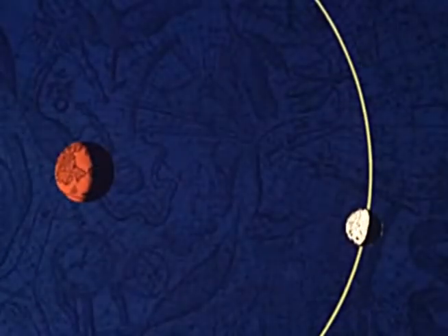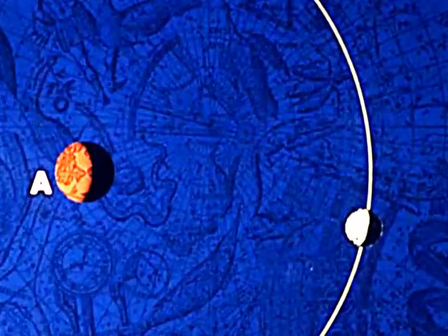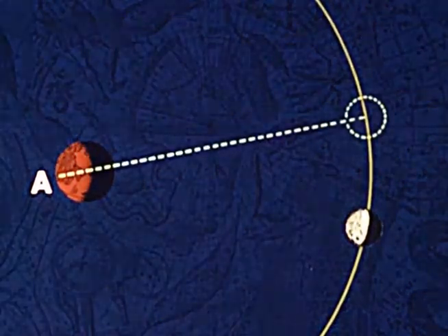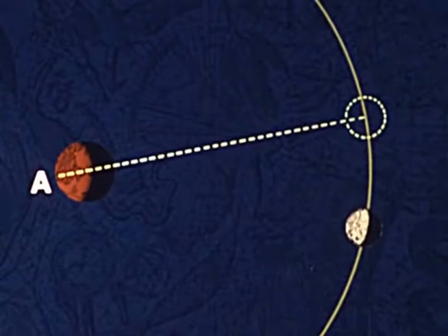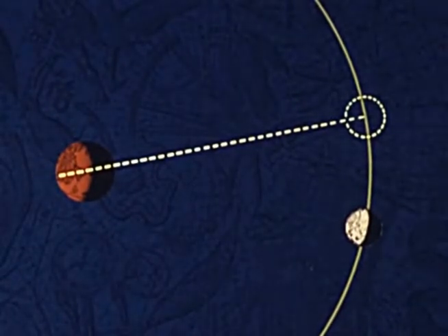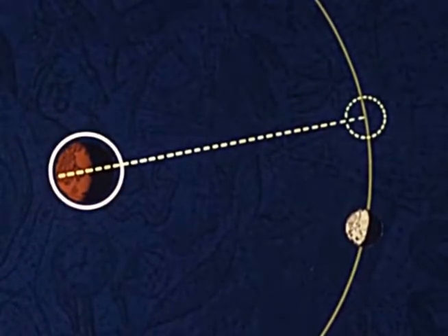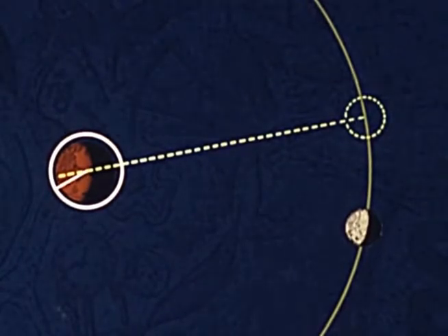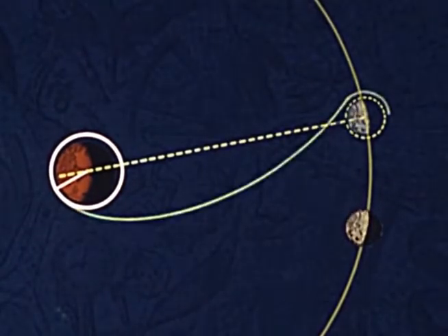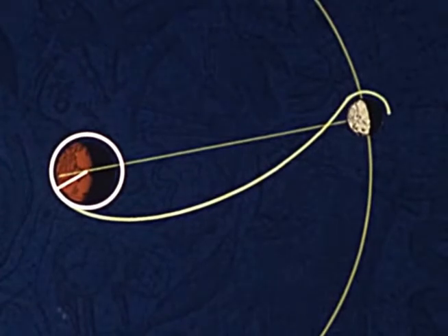Summarizing then, the antipode, or point opposite, will be calculated from the moon's position at time of spacecraft arrival, not at time of launch or injection. The translunar injection burn will occur in Earth parking orbit. The engines will be ignited so that the effective point of injection will occur a few degrees after passing the moon's antipode on the surface of the Earth to lead the moon and compensate for lunar gravity.